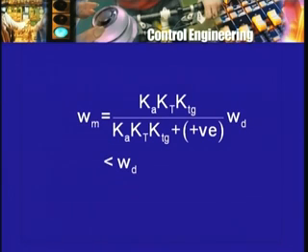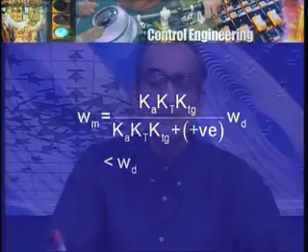So this sort of proves that if you choose the reference voltage equal to the tacho generator voltage produced at the desired speed, then the drive will not work properly. In the sense, it will not even run at the desired speed. I told you that this is absurd, because we can certainly make the drive run at the desired speed under the rated or the nominal conditions. So if we know the load torque, full load torque, let us say, if we know all the coefficients, etc., then we can certainly make the drive run at the desired speed.